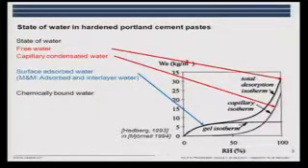Here you can see that the gel isotherm is constant above 45% relative humidity, which is not the full truth. I'll show you some slides afterwards. So at the upper relative humidities, we have first the free water, which is up here, capillary compensated water, and then the surface adsorption. And the chemically bound water would be down here. Due to ions in the pore solution, we will not have 100% relative humidity. We will have, depending on the concentration, 98 or something like that.